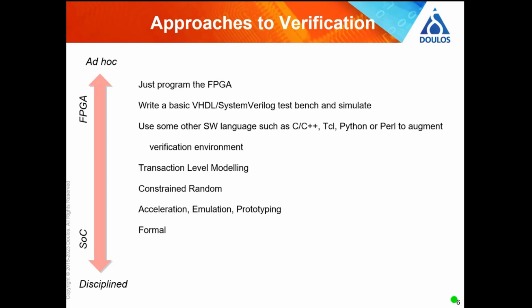Something else, really cool technology: formal verification. This is mathematically proving that your design is correct, basically. Mathematically proving that your design is the same as another design, so your RTL is the same as your gates, for example, or mathematically proving that your design meets those rules that I've mentioned already. You might call those properties. Well, you do call them properties.